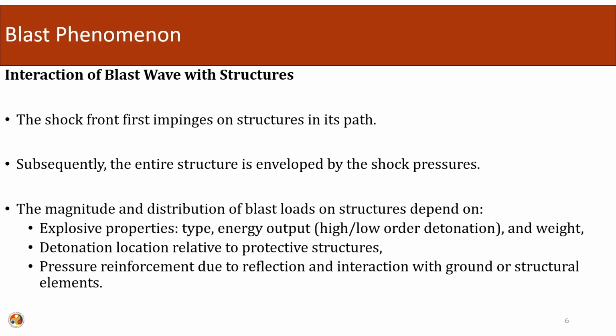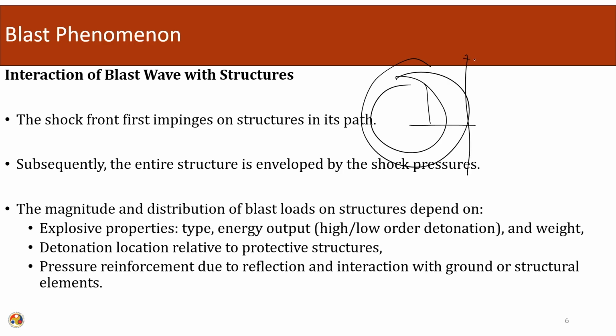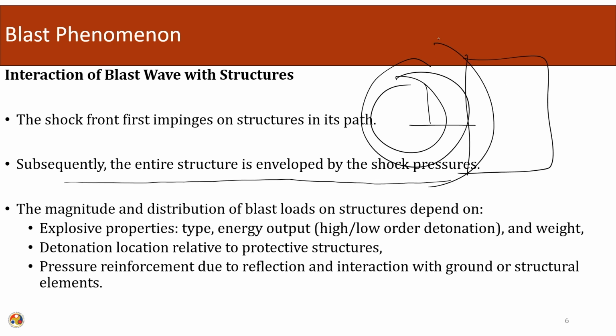Now comes the interaction of the blast wave with structures. The shock front first impinges on the structures in its path. It means that this travelling shock front will hit the structure in its path. Slowly the entire structure is enveloped by the shock pressure. So, after that the shock pressure will be around the entire structure.